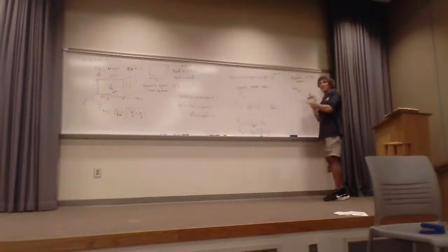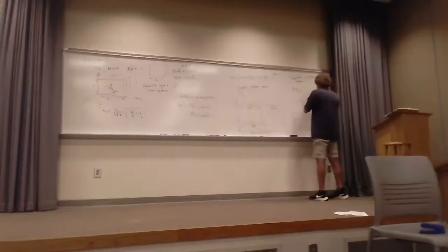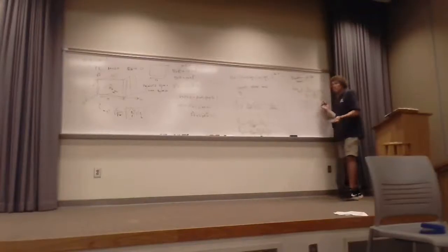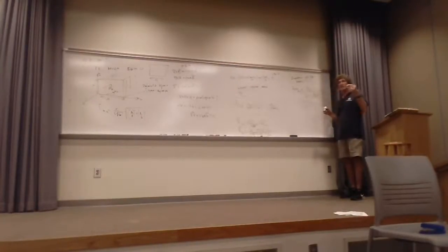There can be a 1-1 mode here, but it'll have a different impedance. Now, that's equal to eta unguided divided by the square root of 1 minus FC over F squared. Now, for this to work and operate, you have to be over FC, and this would be for an MN, by the way. When I put in FC, I'm assuming it's for a given mode, an MN mode. The lowest would be for the 1-0. But when you have that right there, you can see one thing. The closer I get to cutoff, just take a look at this.